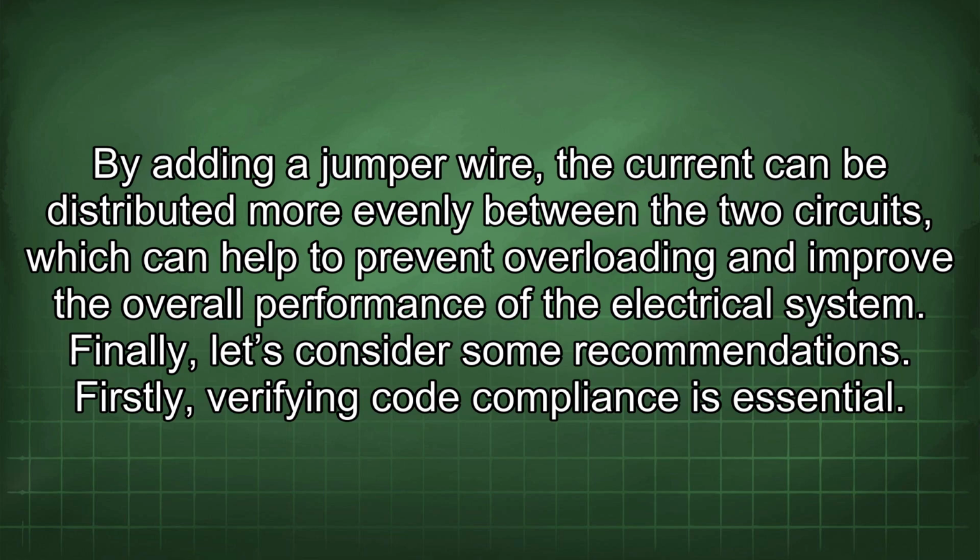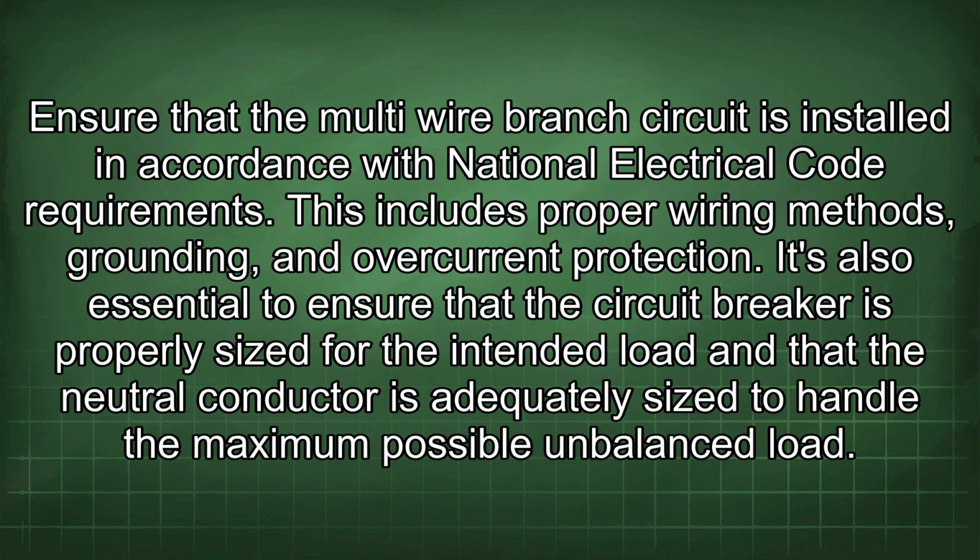Finally, let's consider some recommendations. Firstly, verifying code compliance is essential. Ensure that the multi-wire branch circuit is installed in accordance with National Electrical Code requirements. This includes proper wiring methods, grounding, and overcurrent protection. It's also essential to ensure that the circuit breaker is properly sized for the intended load and that the neutral conductor is adequately sized to handle the maximum possible imbalanced load.